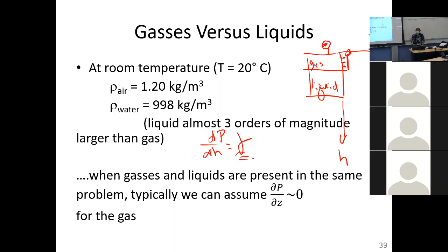the specific weight of the gas is so small, there's an almost imperceptible change in the pressure past 3 place digits. So if you measure the atmospheric pressure at the top of this room, 20 feet off the ground, and the atmospheric pressure here, and you only had a gauge that read to 4 place accuracy, you wouldn't be able to see the change in the pressure. You have to go over great distances in the gas. Once we hit the liquid, then we would see a change in pressure.